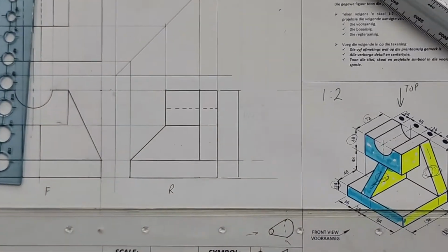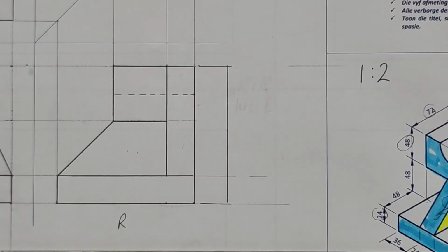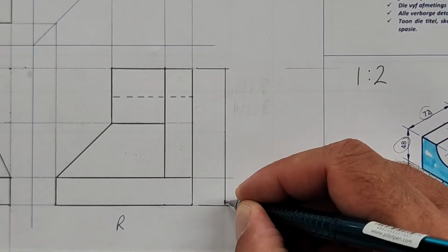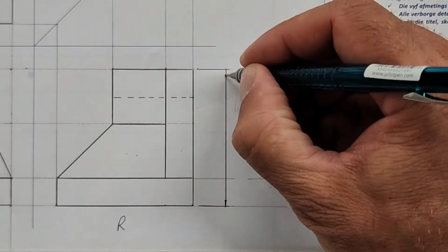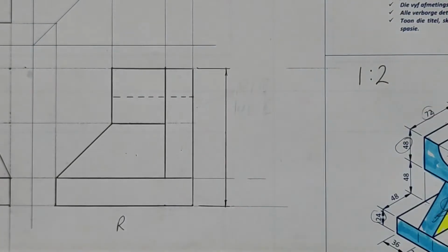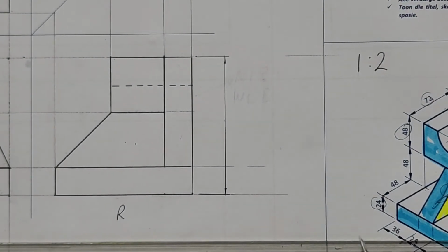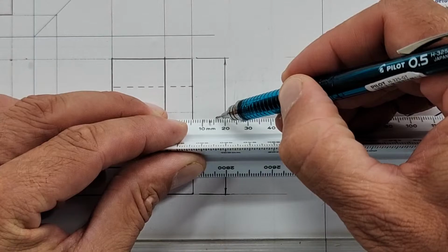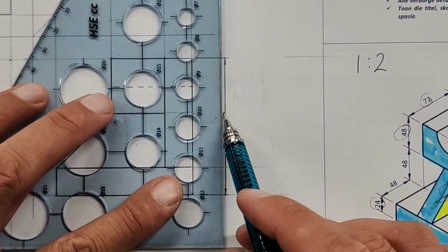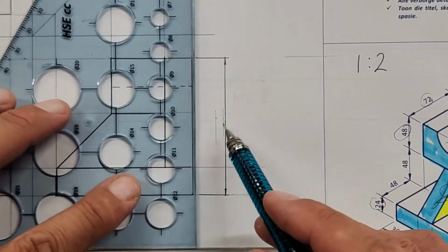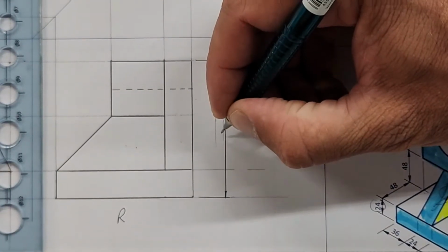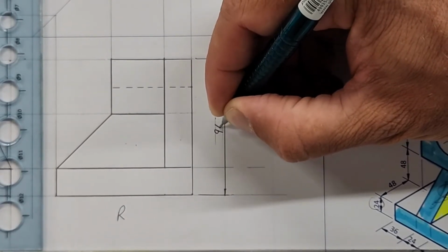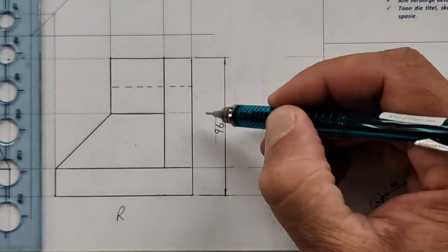Okay. Yes. Is it 15 millimeter extra, 15 millimeter in total? Yeah, in total. Okay, and then an arrow. That arrow doesn't look like you're doing archery. Okay, you're not Robin Hood. It's small, very simple like that. Then in the middle of this line, you do a 1 millimeter, then a 3 millimeter construction line. Construction line. And what do you write there? 90. Oops, sorry. In the middle, 96.